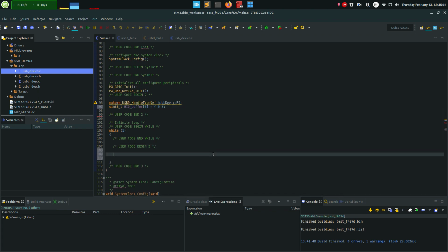Firstly, let's fill the buffer with appropriate data. In our case, let's also utilize the modifier key, so let's create a capital D. Capital D is actually D and the shift modifier. We said that the modifier is the first byte. So HID buffer, the first byte is going to be shift.